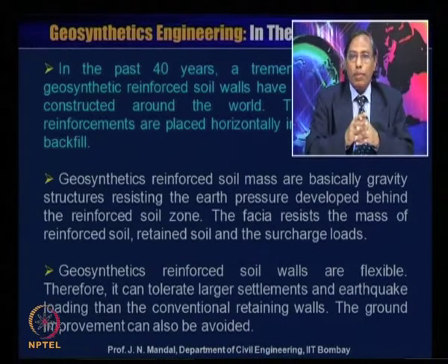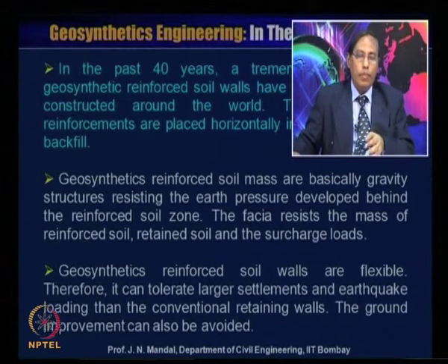Geosynthetic reinforced soil masses are basically gravity structures resisting the earth pressure developed behind the reinforced soil zone. The facing resists the mass of the reinforced soil, retained soil and surcharge load. Geosynthetic reinforced soil walls are flexible, therefore they can tolerate large settlement and earthquake loading better than conventional retaining walls. Ground improvement can also be avoided.